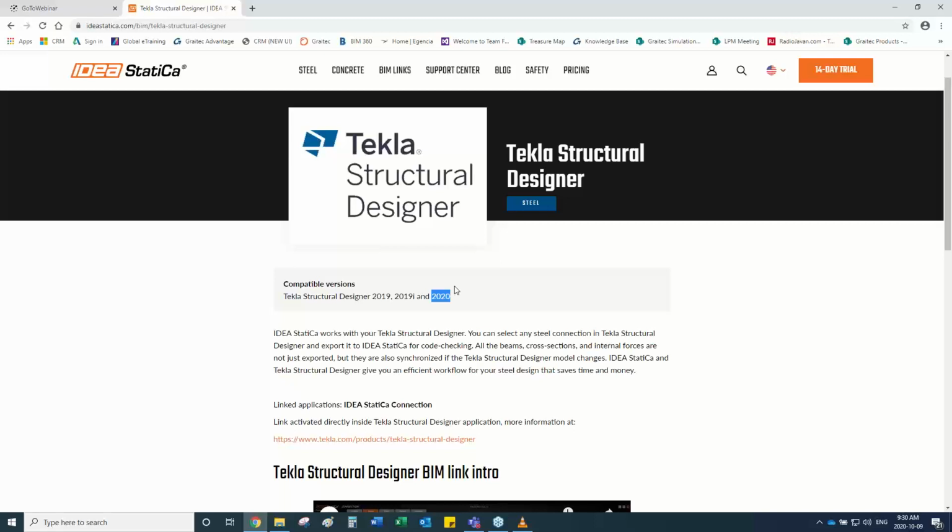I have another comment which says, Check Missing Weld is an excellent tool. Yes, it is a very good tool. I have used it, especially when you sometimes have tricky points or tricky geometry where you cannot define the weld manually. You can use that tool and it will automatically add that special weld in that specific place. So it is a very helpful tool.